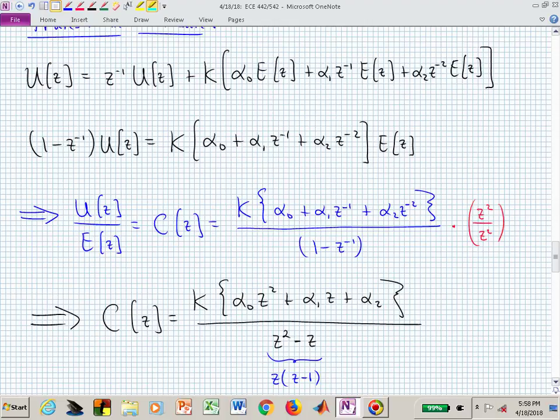So we actually have to trade off those two, don't we? We need steady state accuracy when we put a pole at z equal to 1. That's what we're focusing on, steady state accuracy. That is then going to be traded off by transient performance. And we will achieve the transient performance adjustment in the numerator by selecting those coefficients.